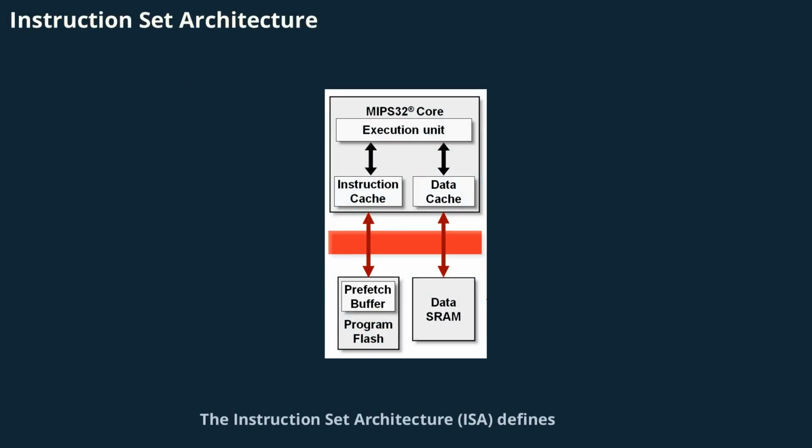Instruction set architecture (ISA) defines the interface between software and hardware. It determines the available instructions, addressing modes, and data types that firmware can use. For STM32 devices, the ARM Cortex-M ISA features the Thumb-2 instruction set, supporting both 16-bit and 32-bit instructions, conditional execution, and hardware multiply and divide. Understanding the ISA is essential for writing efficient, high-performance firmware that fully leverages the MCU's capabilities.